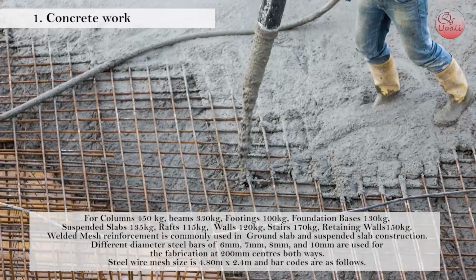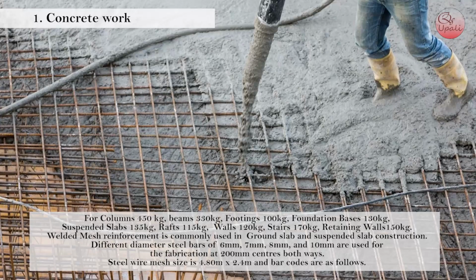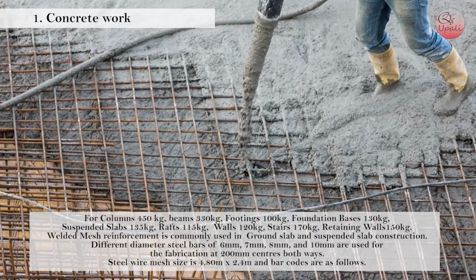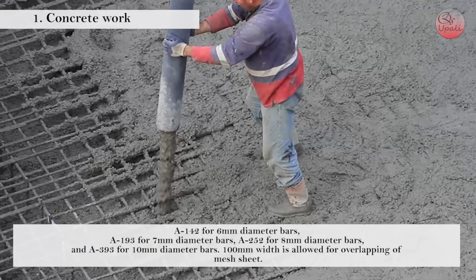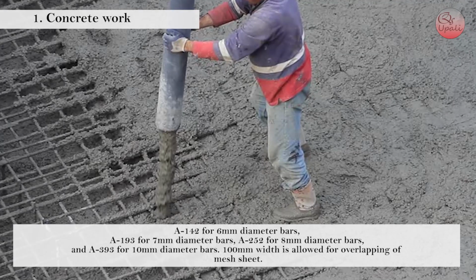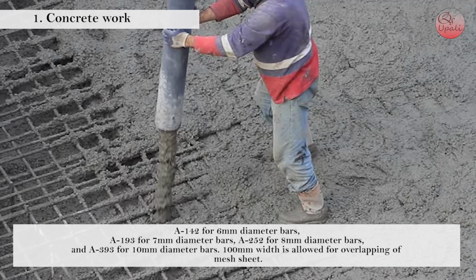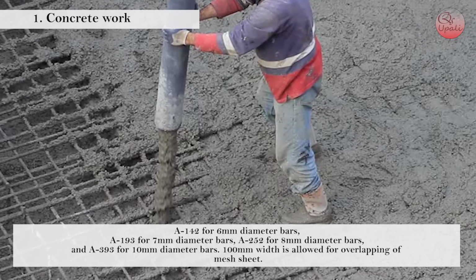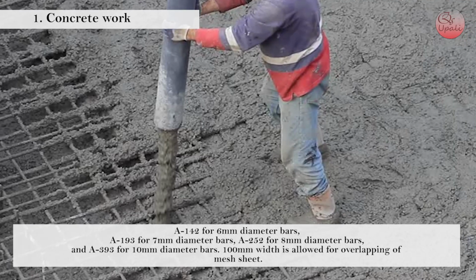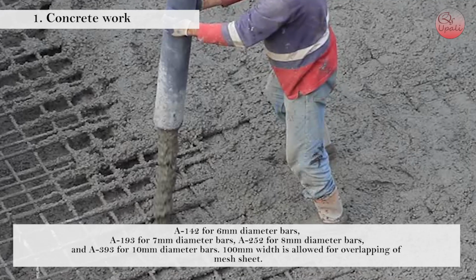Steel wire mesh size is 4.80 meter by 2.40 meter and bar codes are as follows. A142 for 6 mm diameter bars, A193 for 7 mm diameter bars, A252 for 8 mm bars and A393 for 10 mm diameter bars. 100 mm width is allowed for overlapping of mesh sheet.